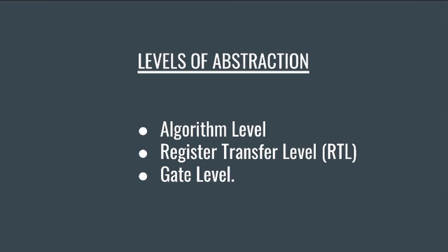Coming to the RTL, this RTL description has an explicit clock, and all operations are scheduled to occur in specific clock cycles. But there are no detailed delays below the cycle level. A single global clock may be preferred. Retiming is a feature that allows operations to be rescheduled across these clock cycles. RTL specifies the characteristics of the circuit by operations and the transfer of data between the registers.